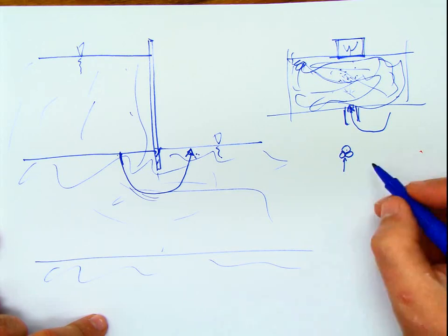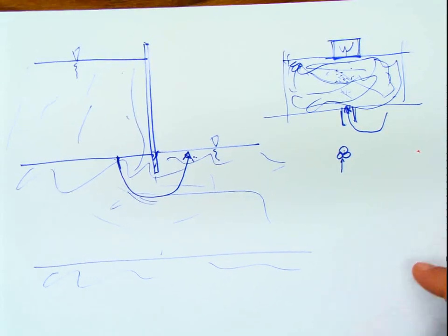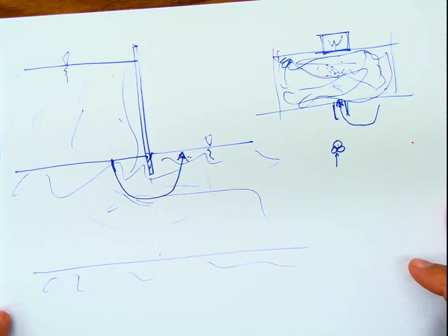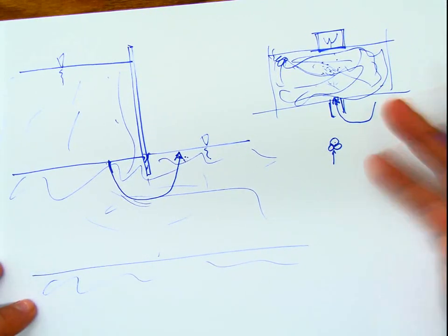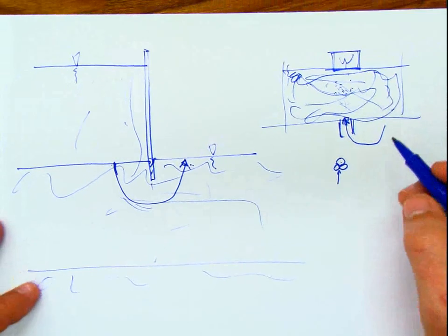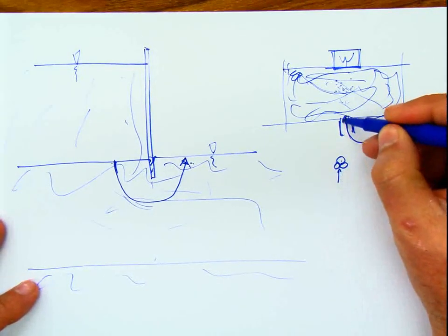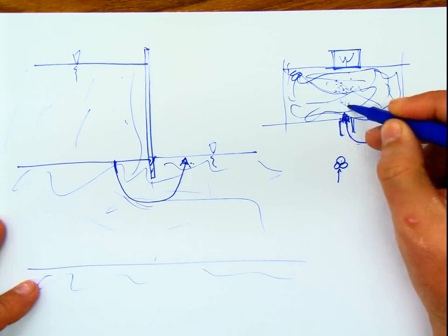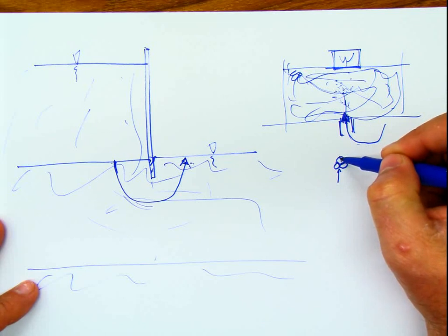And remember, that happens with the critical hydraulic gradient, at the exit, etc. I'll show you how to calculate it: the critical hydraulic gradient is gamma submerged of the soil divided by gamma of the water. But the fact is, whenever you have this flow of water acting in this direction, that friction is becoming lost.